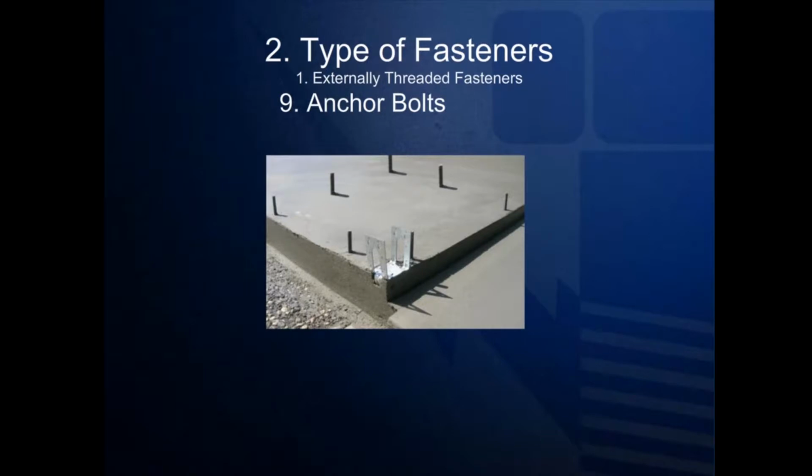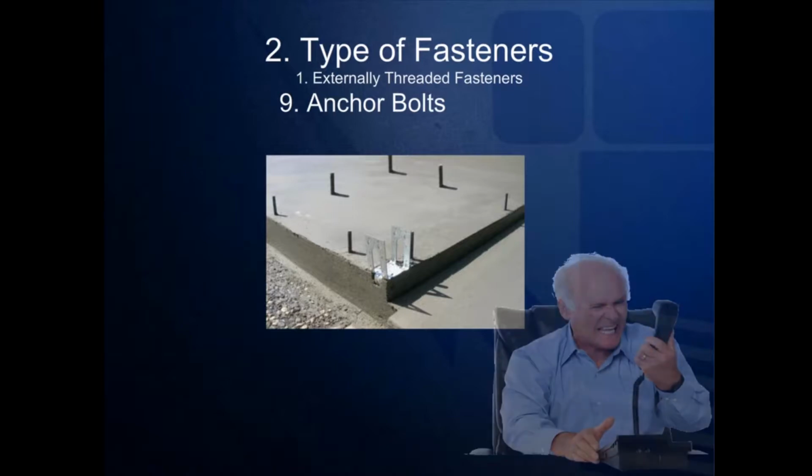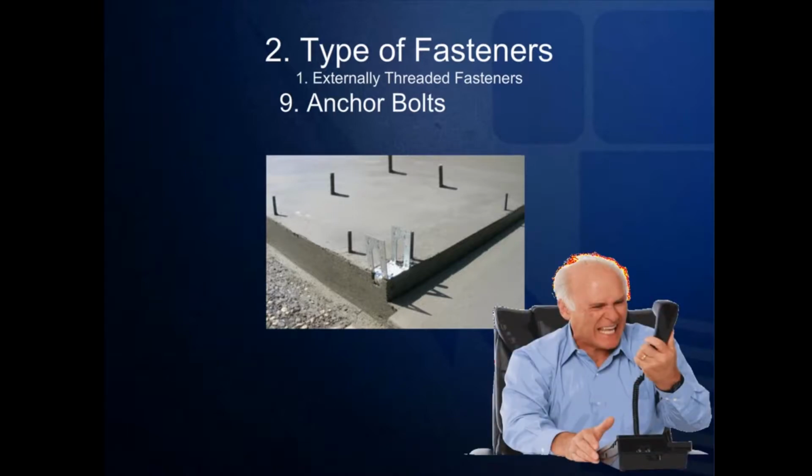It is important that care is taken during the hot-dip galvanizing application, because if you end up with a lot of galvanizing stuck in the threads of the anchor bolt, you won't be able to put a nut on it. You can imagine how upset a customer would be if they have their anchor bolts already poured into place and they can't get nuts on them.